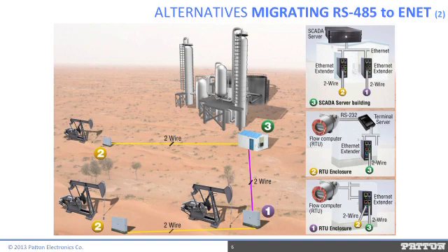The terminal servers turn the serial RS-232 or RS-485 port into an Ethernet port. Scenario number 2 is deploying new communication links using Ethernet communications. In this case, select the flow computer with the Ethernet interface. The installation of the communication link is very simple.